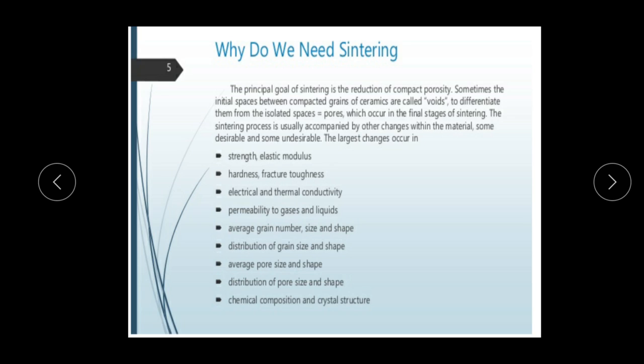Some desirable properties we can discuss here. Strength, elastic modulus, hardness and fracture toughness will be improved. Electrical and thermal conductivity will be improved, as will permeability to gases and liquids. Other changes include average grain number, size and shape, distribution of grain size and shape, average pore size and shape, distribution of pore size and shape, chemical composition and crystal structure.